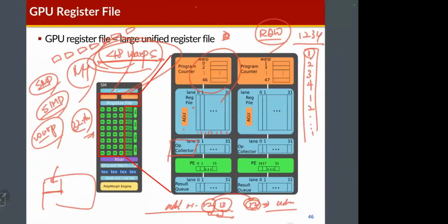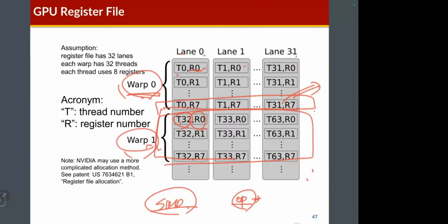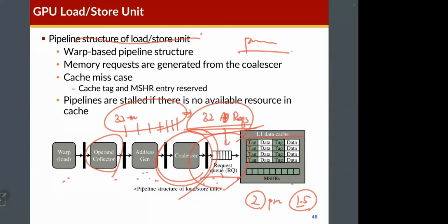If you look at the execution units in the GPU architecture, you can find that there are many CUDA cores, which are simple cores for integer or floating point operations. Also, you can find the load store unit and the special function unit. Recent GPU architectures also include tensor cores, which just execute matrix-related instructions.